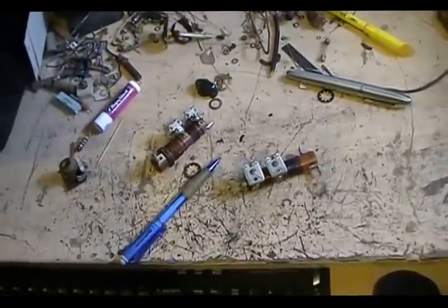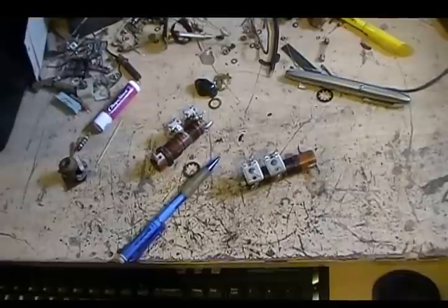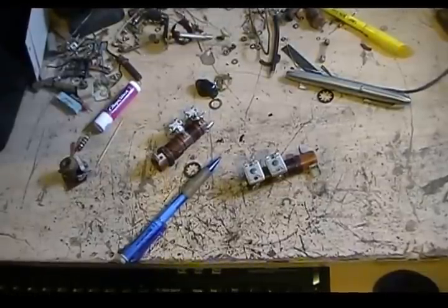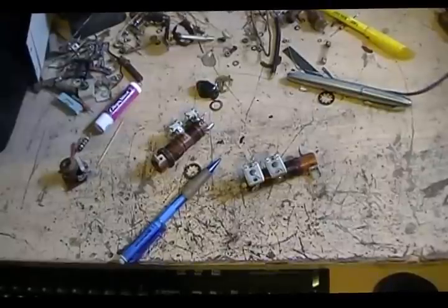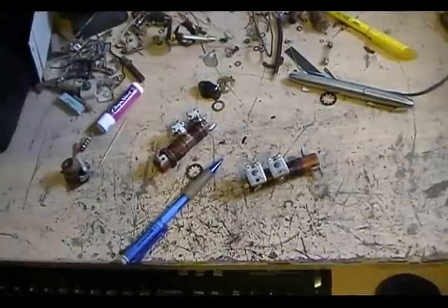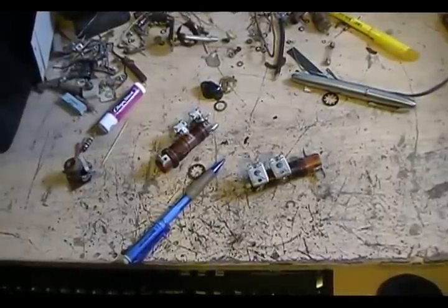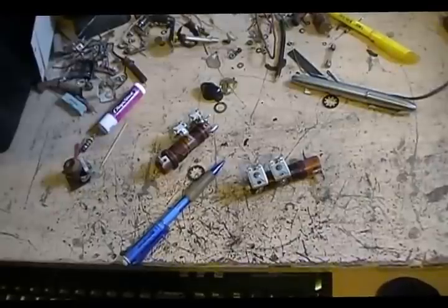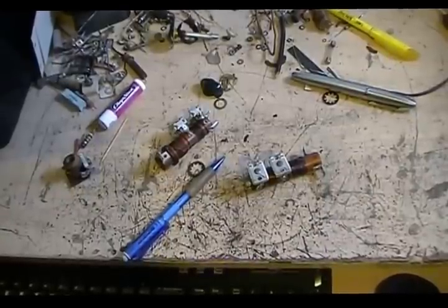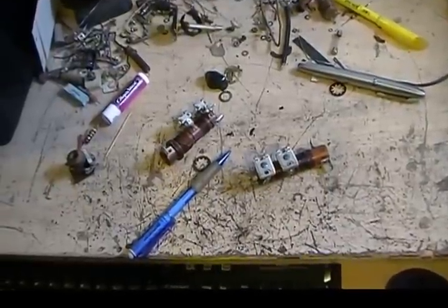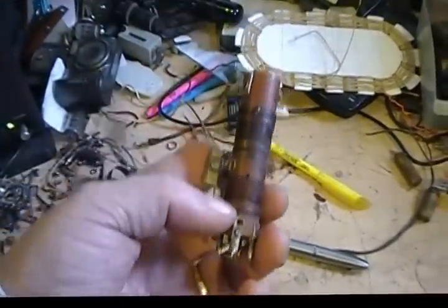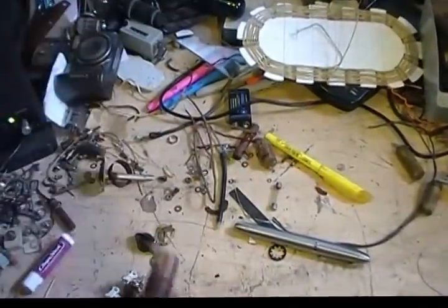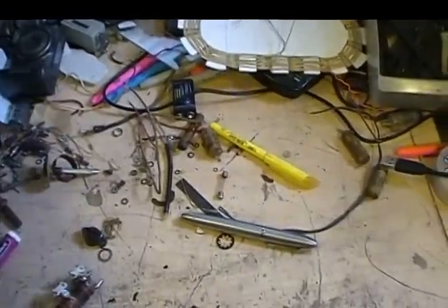And then only tack it in. And only deal with, if you got multi-band, only deal with the broadcast for the time being. Tack them in, if you got it figured out which way they should hook, and get the rest of the radio done, and then fire it up and see if it works. If it works, you're good to go. You can finish off the rest of the coil form and the rest of the coils, get them all hooked up, everything permanently hooked up, and call it good.